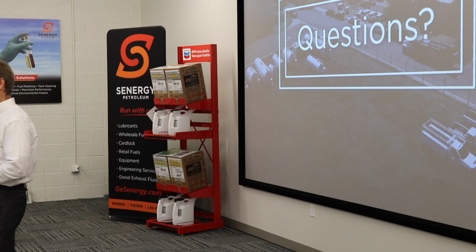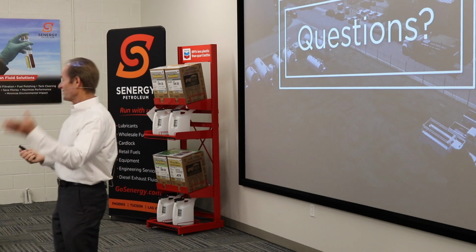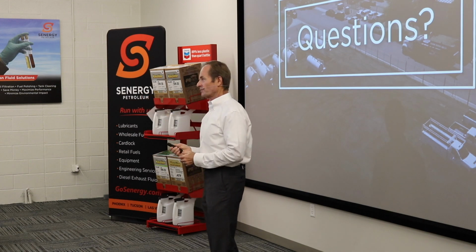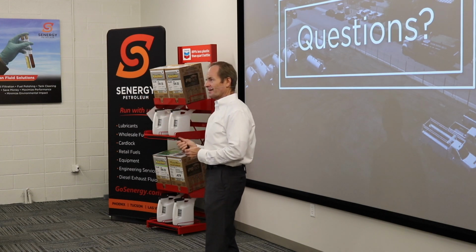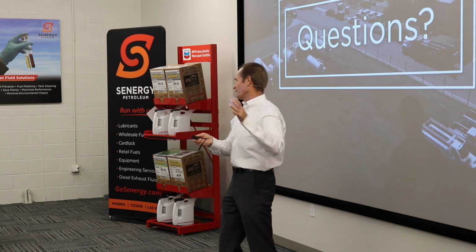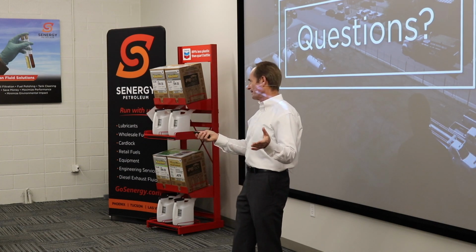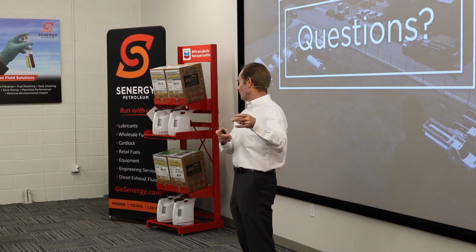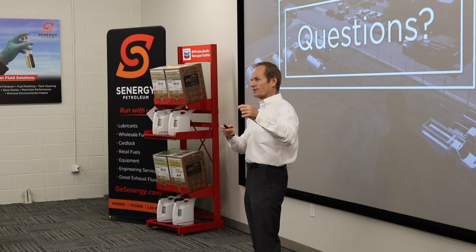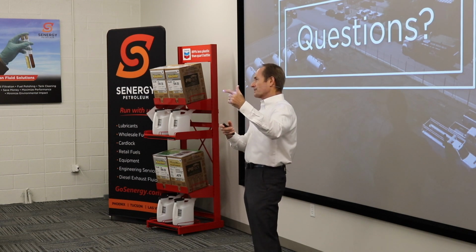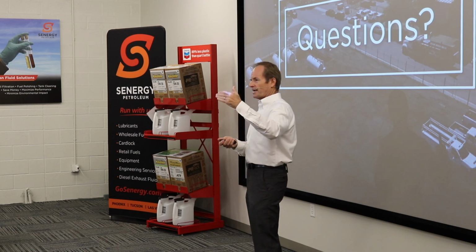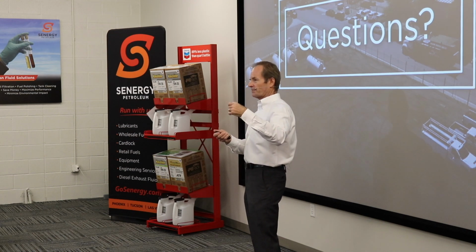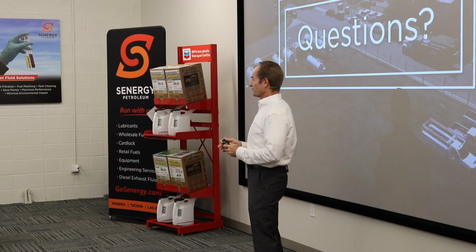Oh, okay. Yeah, the question is, I've seen people use transmission fluid in power steering, and is that legit? And it's really interesting. Well, not really interesting. Only interesting if you're a lube geek like me. Back in the day, the old Dexron 2 days, yeah, that's exactly what you did. Starting probably in the 70s or 80s, the pressures in power steering systems went up, and it was no longer providing enough protection.